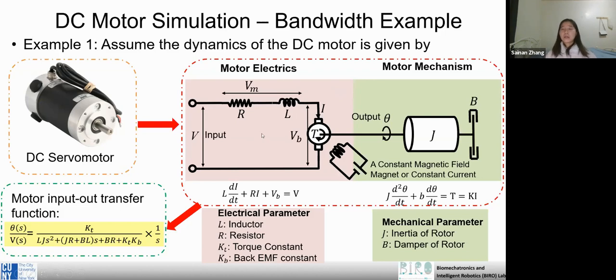For example, when a human walks, the exoskeleton requires at least about 20 newtons. This motor may only generate 1 Newton or 0.5 Newton. It's too small, so that is why we need a gear ratio. That's why the conventional actuator exists.